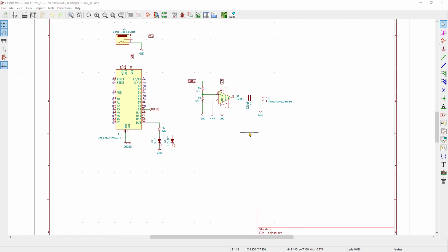So our first step, whenever you're designing a PCB for the first time, is to make sure that your schematic is right. Using software EDA tools, electrical design tools, you always have the schematic and the PCB linked, which means that as long as your schematic is right, your PCB really can't be wrong. You can design it in a way that isn't as effective or as efficient or might not meet some of the frequencies, but it'll at least be electrically connected correctly. So it's important to start from the schematic.